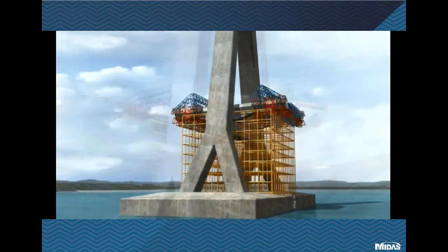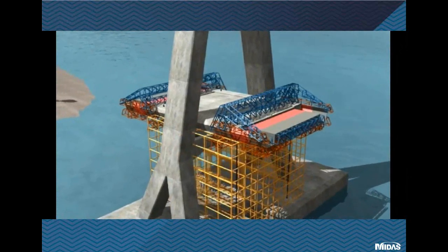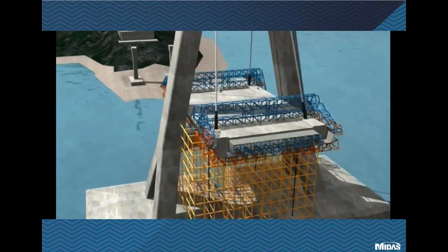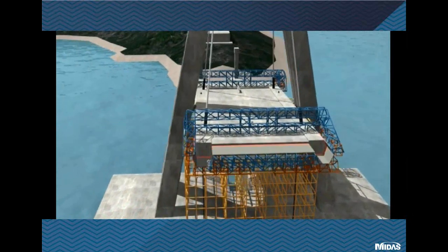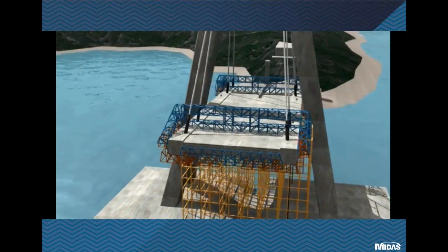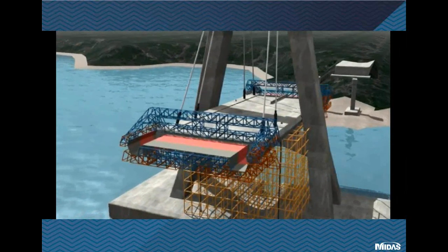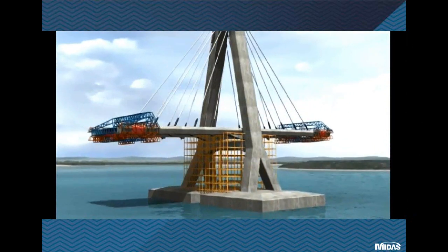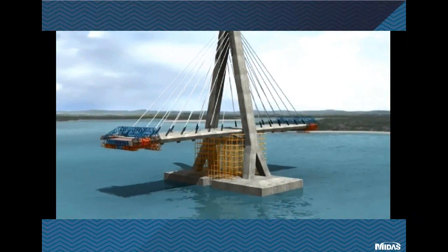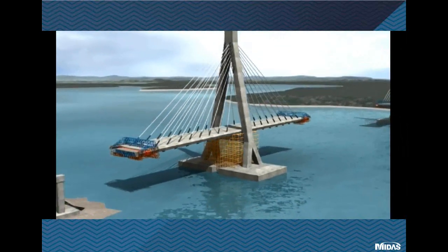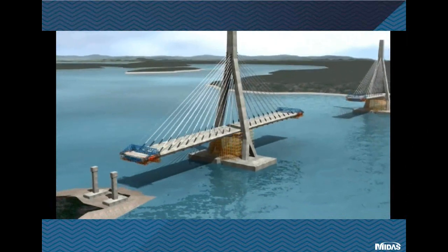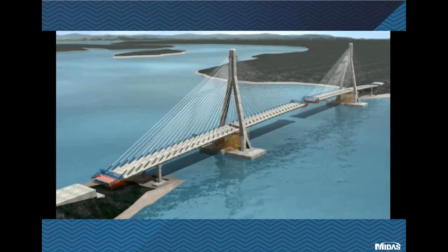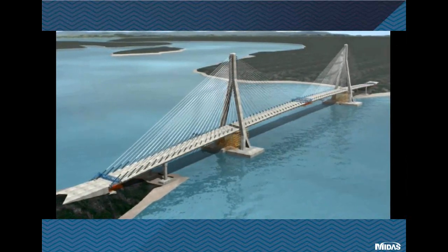Now is installation of travelers. We start construction of the bridge deck, including installation of stay cables, segment by segment. When arriving in the position of intermediate piers, we propose a temporary fixing between the deck and intermediate piers to allow the uplift force.